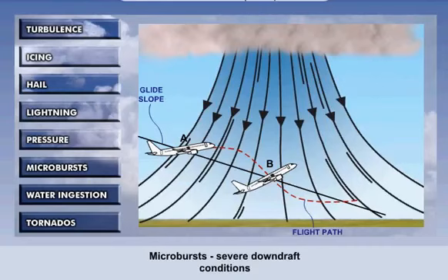However, if the aircraft continued to this stage, it would be exposed to massive downdrafts. Now the aircraft has very low power settings, a decaying airspeed, and massive loss of lift. Lastly, at this point, the aircraft has tailwinds which will significantly reduce the performance and possibly cause the aircraft to contact the ground prior to reaching the runway.